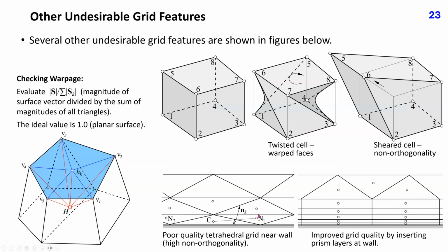With unstructured grids made of tetrahedra, this problem is avoided by creating prism layers along walls, with a gradual expansion of prism with distance from wall. The height of the first tetrahedron attached to prism layer should not be more than twice the thickness of the prism with which it is sharing a face.